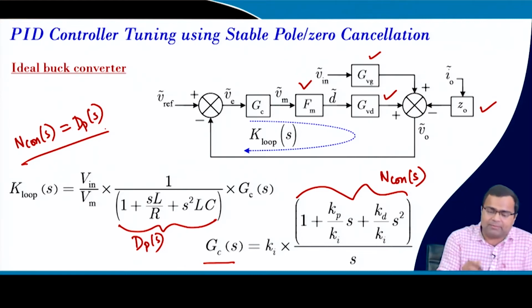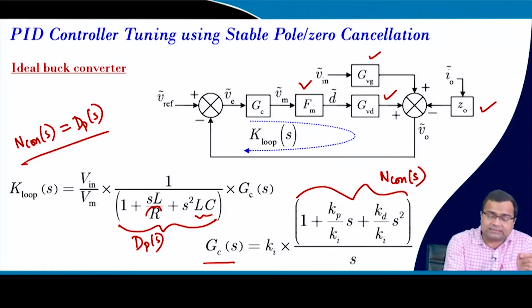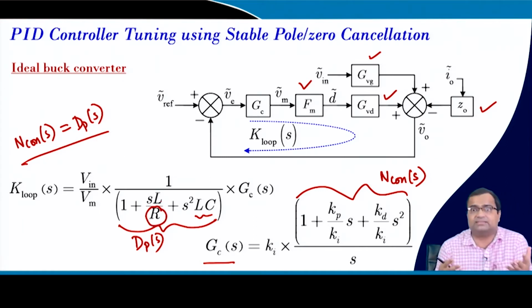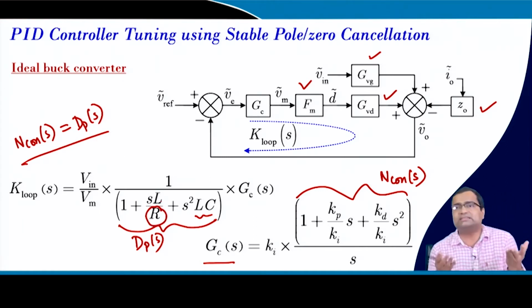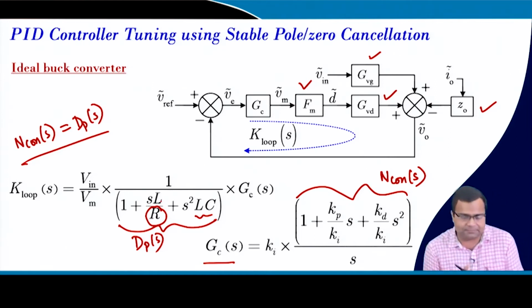The problem in this method is that the LC parameters are reasonably known because they are known from the design, because we have selected L and C, though there can be slight variation, like plus minus 10% in L and C, but the resistance is something which varies. So, we do not know what the resistance value will be, right. It is not easy to know, because you can use a load estimator, but that is not a good technique.